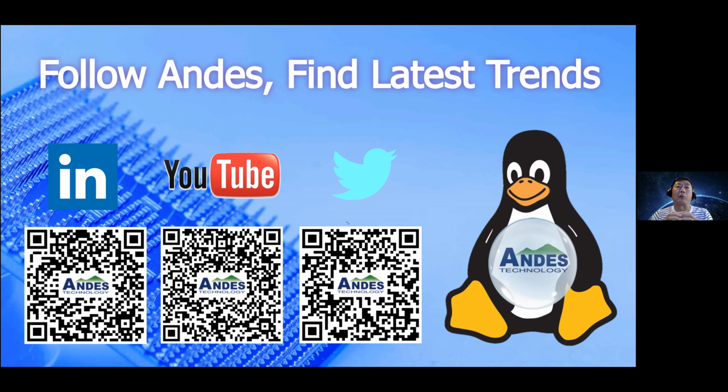But now if you're talking about a compute type of instruction that you want to add, the way that we designed the RISC-V processor, it's very simple to add a special custom vector instruction. We just need to know some really basic information regarding the latencies and the throughput and all that. Then we can actually add that custom instruction in. And our design is very simple, that also allows us to add more functional units.